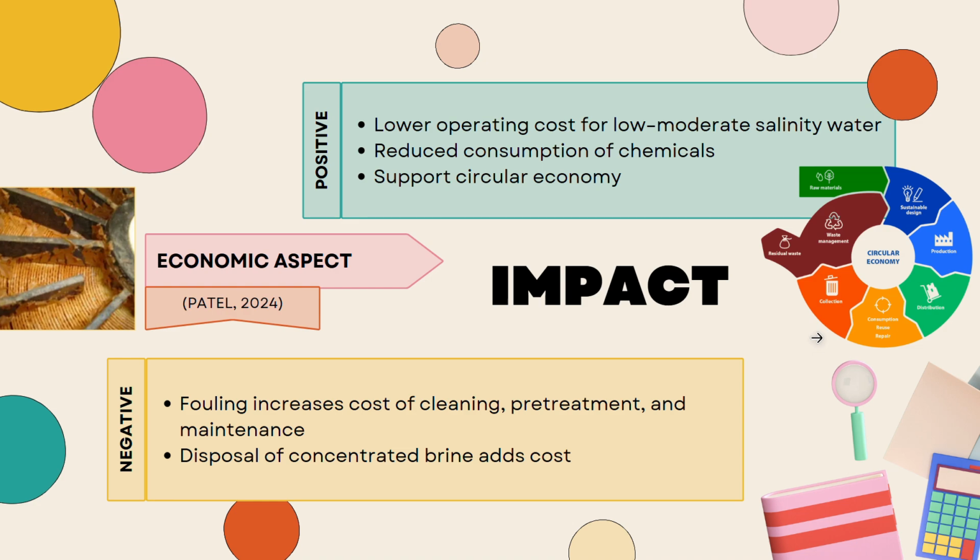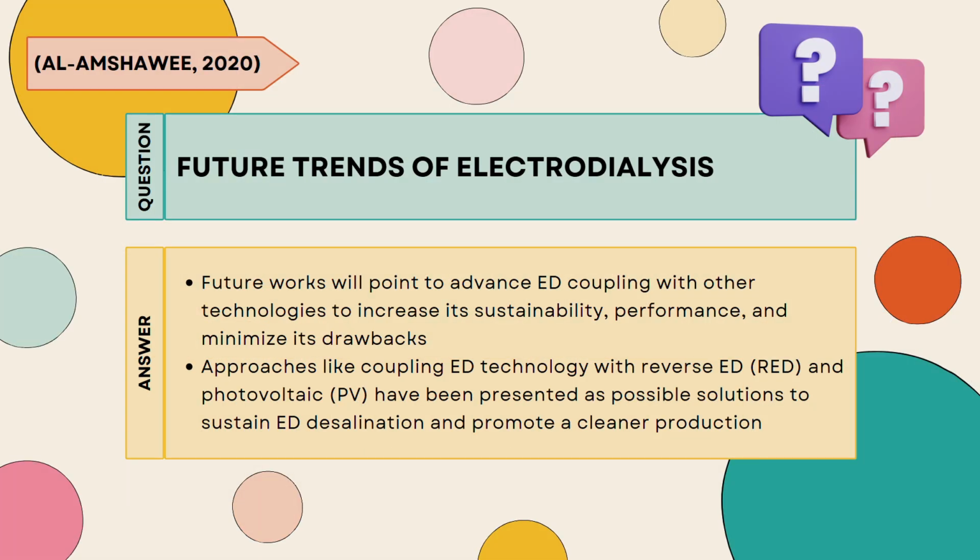For the negative impact, the fouling membrane will increase the cost of cleaning, pre-treatment, and maintenance. Right over here, it is a fouling membrane. Besides that, the disposal of concentrated brine will also add cost. So now let us learn about the future trends of electrodialysis.